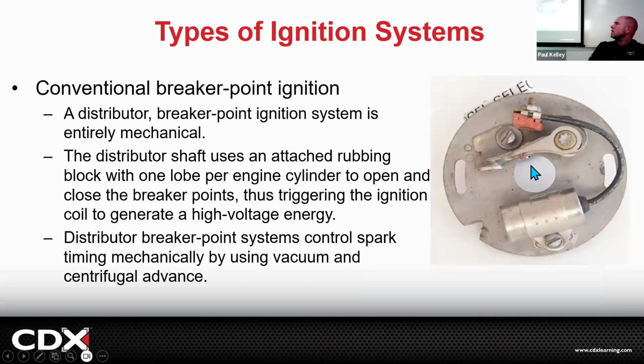In old school like this, there were no timing tables. There was no ignition module, there was no nothing. There was a little vacuum line that went over to this, or they had a mechanical advance. Remember those? The faster it spun, these weights would pull it and twist it a little bit, but it was kind of not precise. If you wanted to tune it, you'd have to literally shave weight off the weights or add weight to it by trying to blob lead onto them or something.